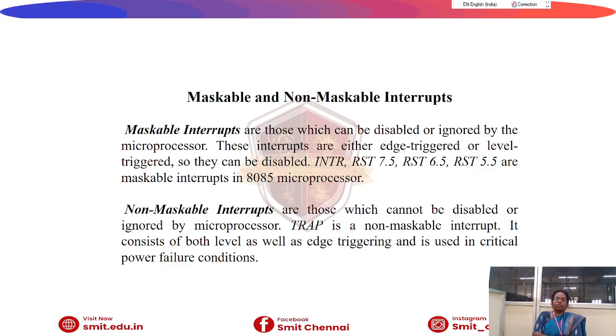Non-maskable interrupts are those which cannot be disabled or ignored by the microprocessor. TRAP is a non-maskable interrupt. It consists of both level as well as edge triggering and is used in critical power failure conditions.